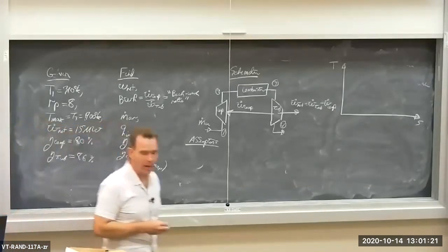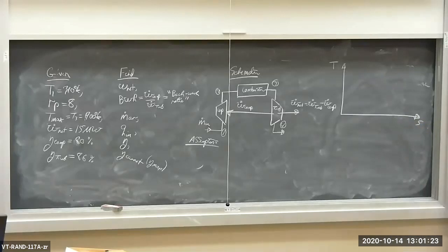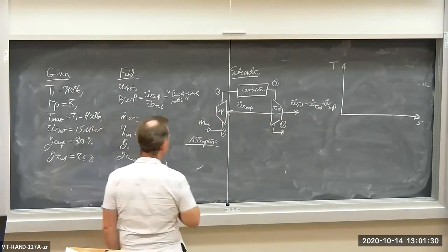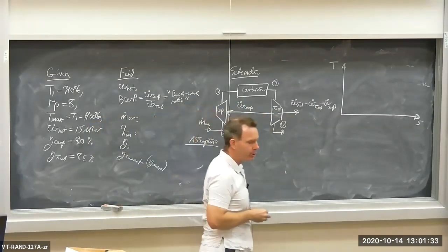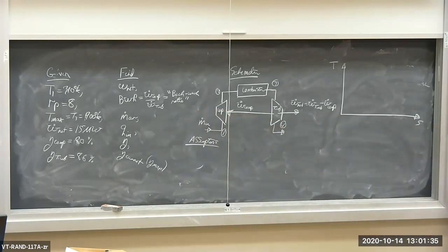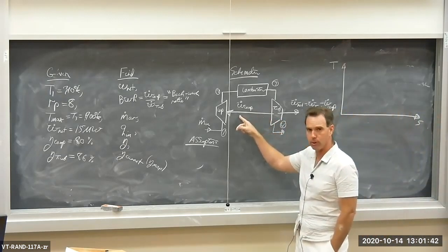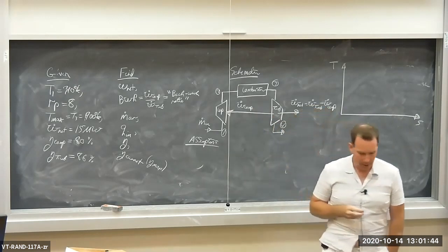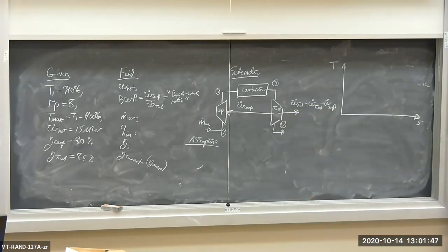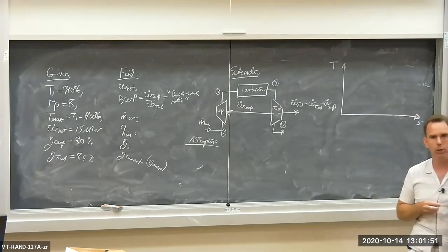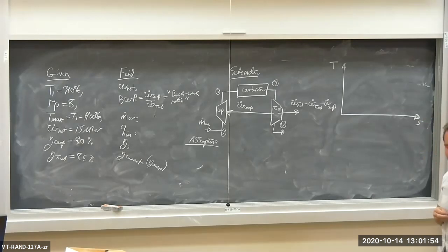Okay, so let's do a little example here involving a non-ideal Brayton cycle. So remember, the Brayton cycle utilizes a compressor which compresses the air, a combustor where the heat addition occurs, perhaps isobarically, perhaps not, and then work is extracted by the turbine, and some of that work or power is used to drive the compressor, and what is left over, if we subtract the compressor power or specific work, is the net work produced or net power produced by the gas turbine.